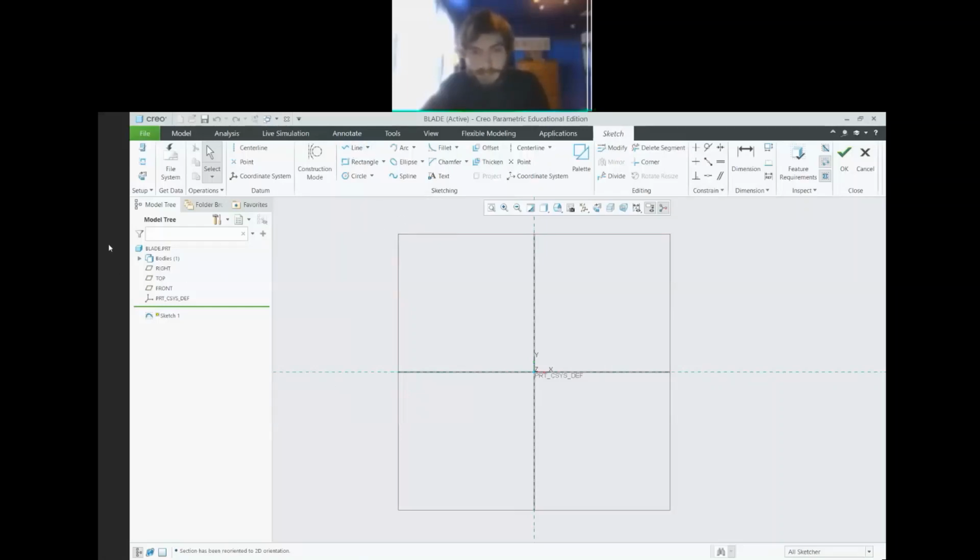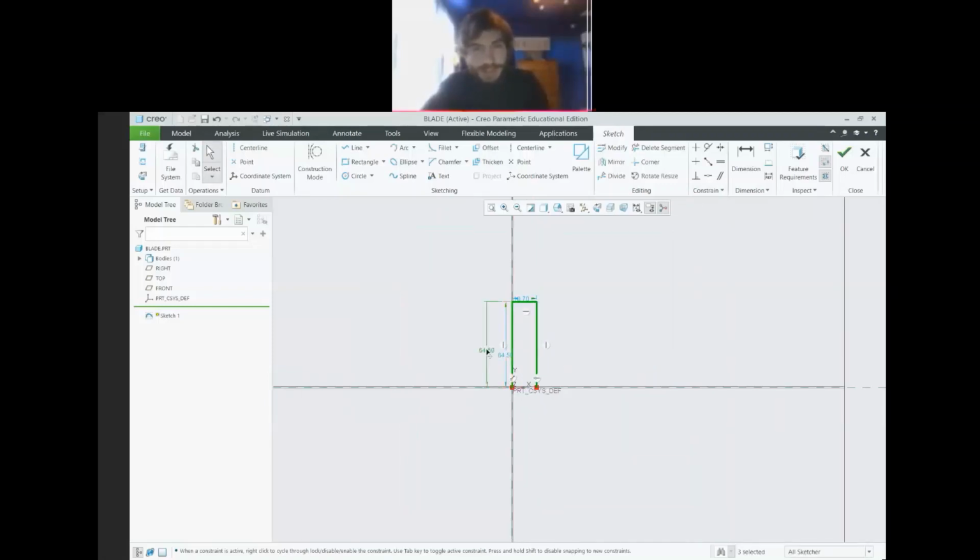Probably the easiest place to start is up at the top. Right, it has a little bit of a straight piece there near the top. So we can go ahead and create our U. Unfortunately, Creo is super annoying. If you create your whole sketch and then dimension something, it'll keep all of the fake dimensions it created.